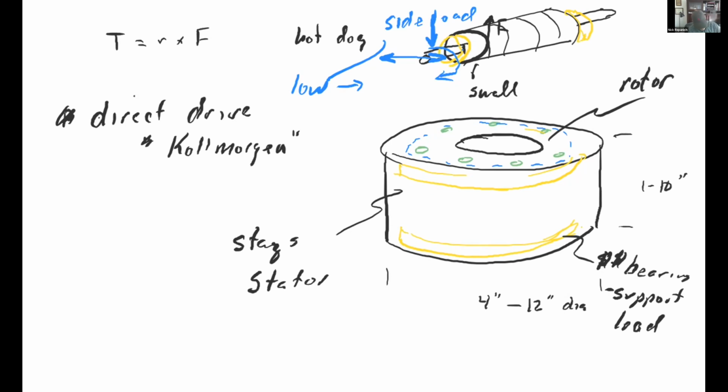There's a big enough bearing in here that you could get away with driving loads directly on the motor shaft. But it's definitely something you always have to look at when you're applying a motor, is what's the side load. The side load, just as a number for this, is probably only about 20 pounds, which isn't very much.